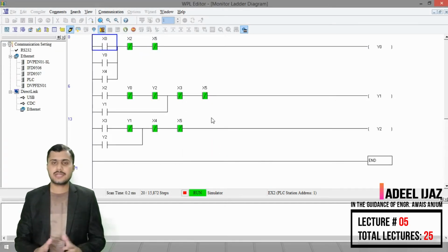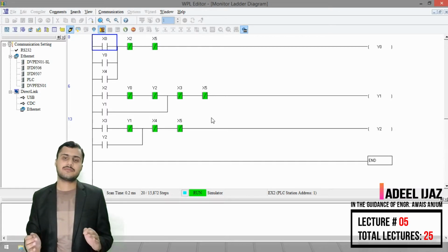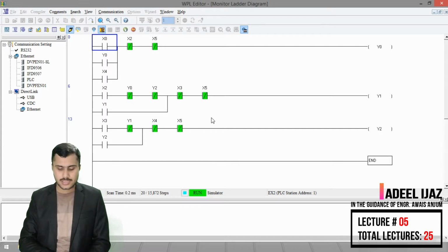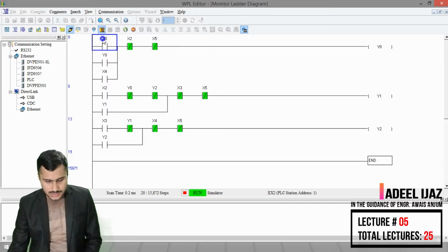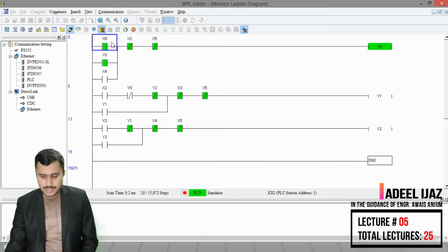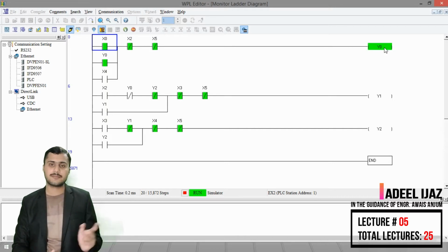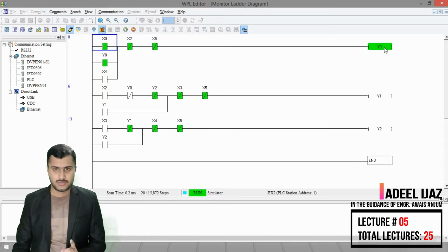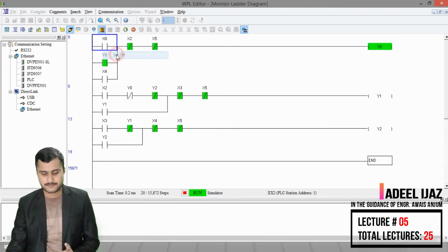Now initially the tank is empty, so first of all liquid number 1 starts to enter into the tank. To start or initiate the process, we need to press the X0 first. So I turn on the X0 and you can see that liquid number 1 starts entering into the tank through the inlet pipe number 1. As X0 is our push button, X0 will turn off.